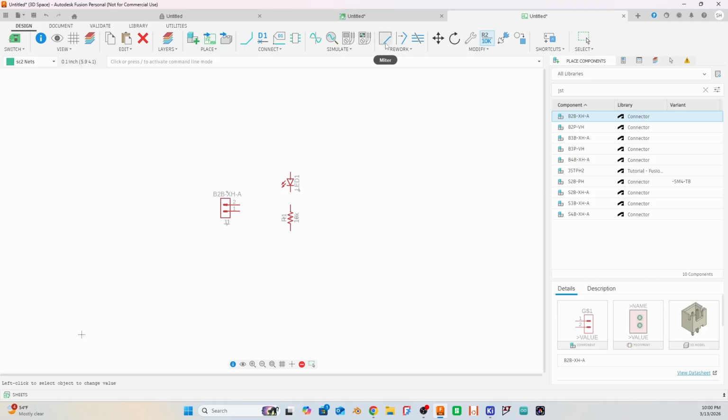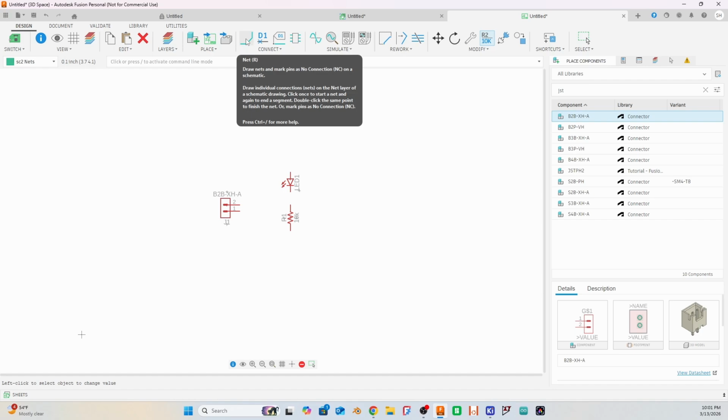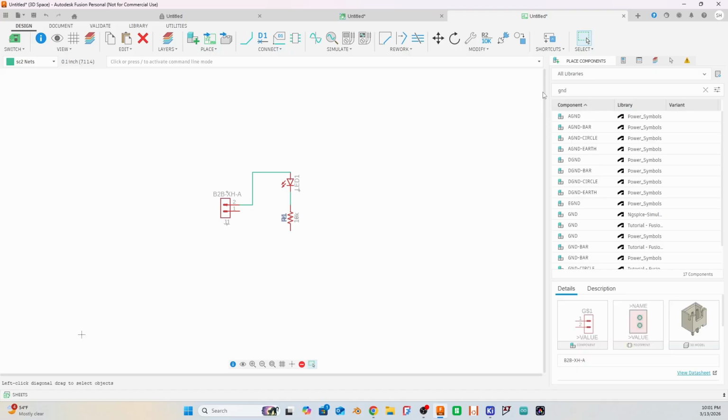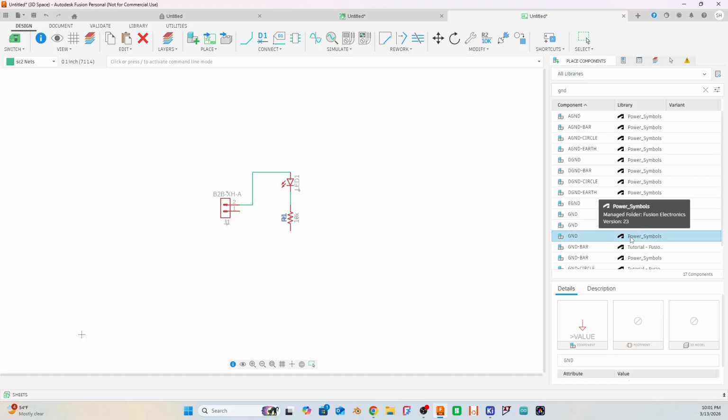Oh, I need to wire the whole thing. That's in the schematic, just a symbol in there. So we need to wire everything in here. So you want to click on this net, or click R, like the shortcuts, and then wire the whole thing. All right. So grab this one, and then let's move the mouse up there, and then wire it like that. One more here. Whoops, we forgot one more thing, the ground, of course. Why not? So click on GND for ground. See, let's grab this one. So simple to me. Maybe not. All right, let's grab this one. Or you can come in here and there's power management and just like this one, power symbols. This.